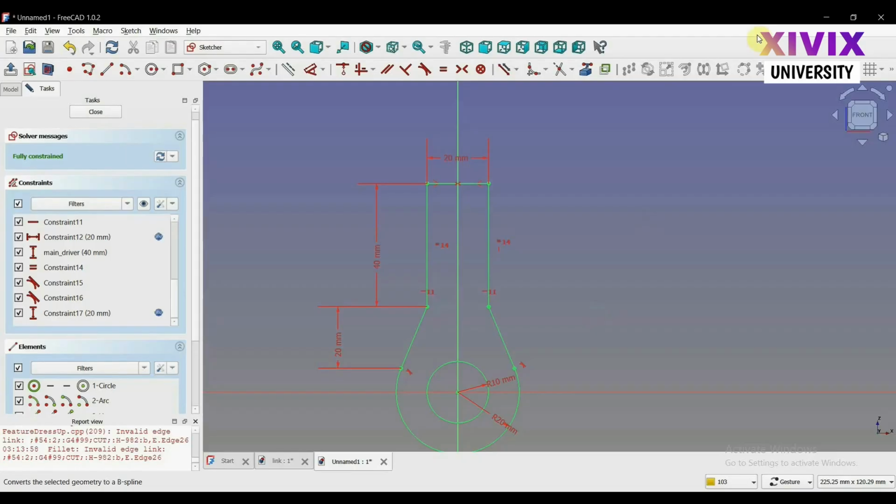So always anchor your sketch into the origin, and also use the symmetric constraint wherever possible instead of duplicating dimensions. That will help you streamline the design process because it dramatically reduces the constraint count, and as a result, it makes your sketch clearer and easier to modify at the same time.